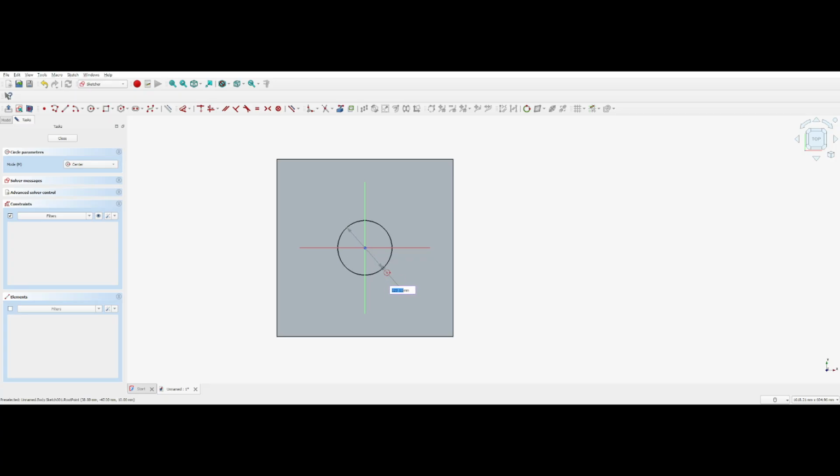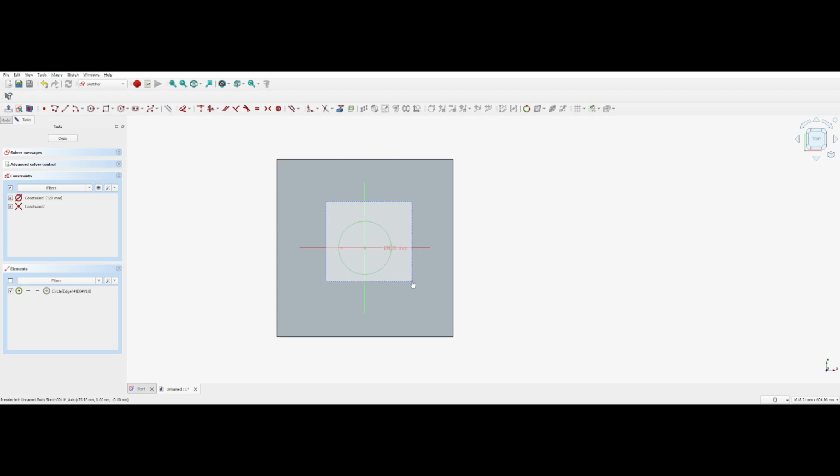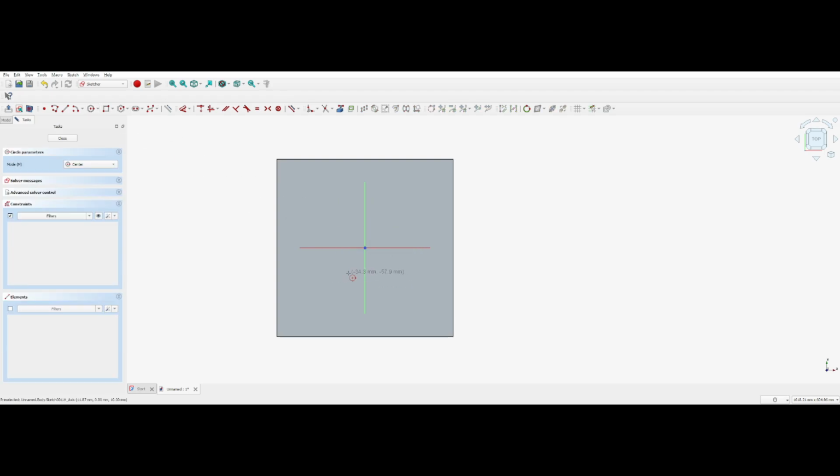Let's say we want our big 120 in the middle as our showpiece. We don't want to make it exactly 120, because then it will rub, it'll buff, whatever. So let's make it slightly bigger. We're not worrying about it being super tight either, so let's make it 123.